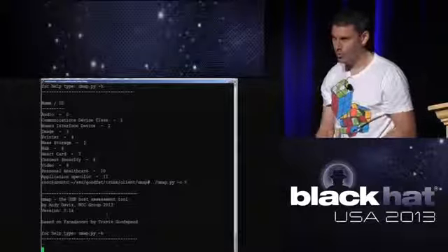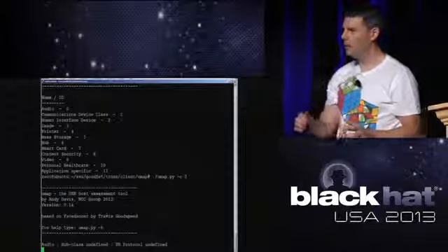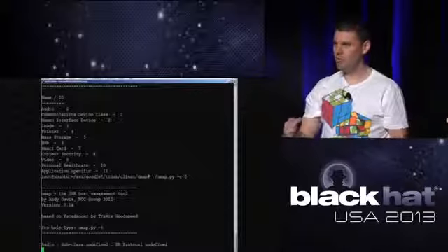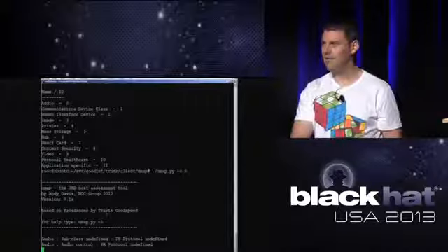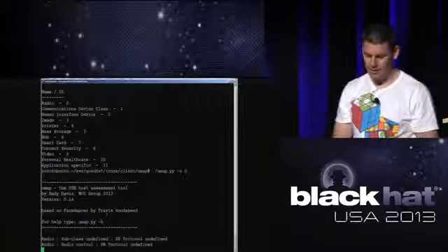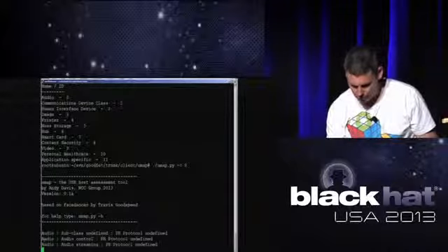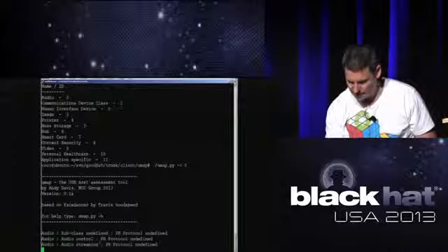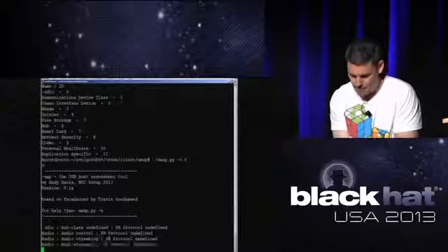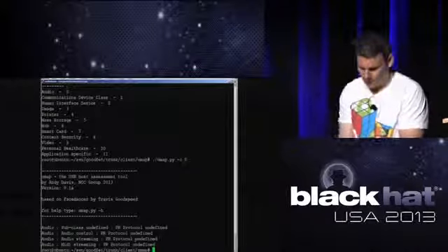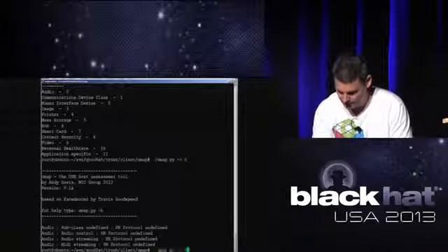It's not super quick. Like I said, it takes about 5 to 6 seconds per enumeration emulation, so you're emulating the process of physically inserting and removing a USB device here. You can see that's the audio class, that's the subclass, and that's the protocol. And you can see that none of those are supported on this particular USB stack.